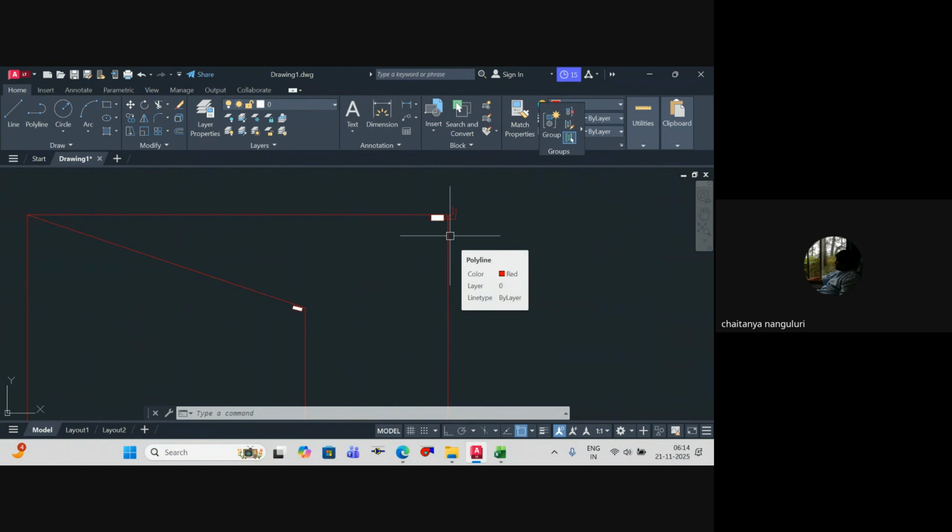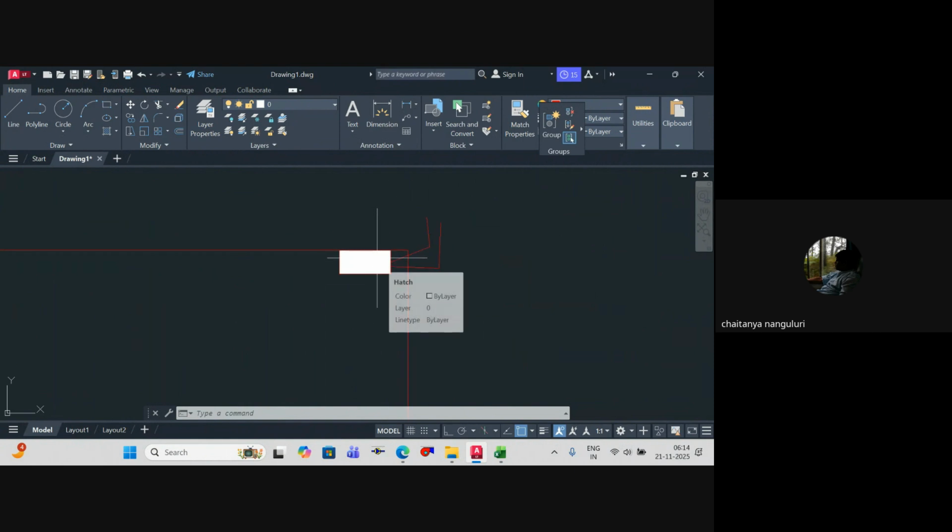If we pull the door flap, automatically this will touch this, right? So then what will happen? The open circuit will become closed and the closed circuit will become open, right? So that you will take as a signal that there's a fire inside the building. Understood? So this works on the simple principle of your fire alarm. If someone opens the door, you will trigger an alarm. So this will be used for all your emergency doors.